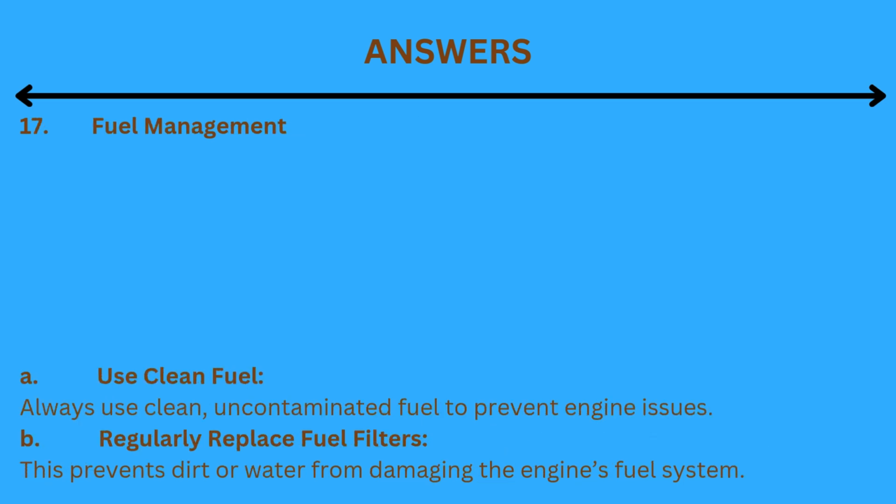17. Fuel management. A. Use clean fuel. Always use clean, uncontaminated fuel to prevent engine issues. B. Regularly replace fuel filters. This prevents dirt or water from damaging the engine's fuel system.